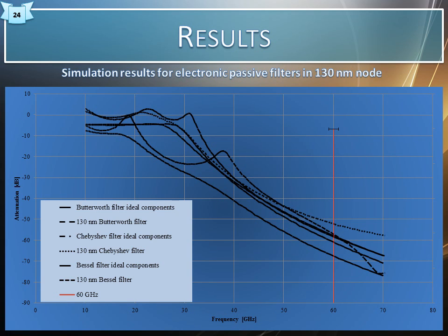These results of the simulated low-pass 7th order filter suggest that through using the component values of the 130 nanometer node, the maximum obtainable attenuation, while still exhibiting low-pass filter characteristics with a minus 20 dB per decade slope, is in the region of minus 60 decibels, as opposed to the required minus 100 dB as proposed with the path loss function presented earlier.